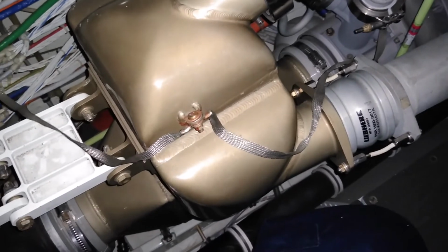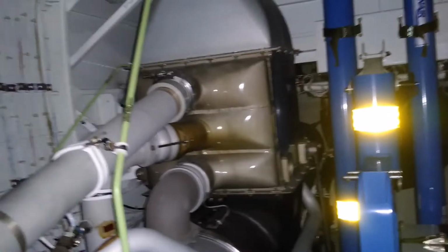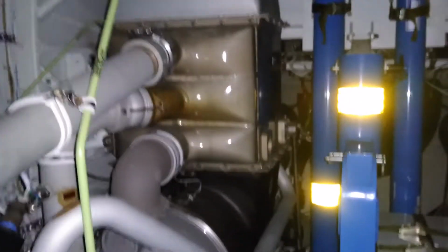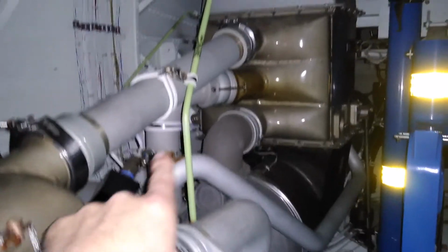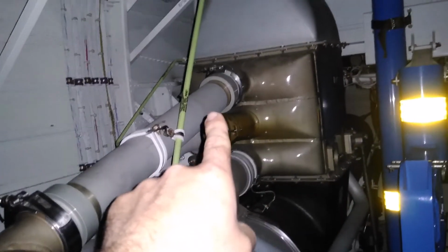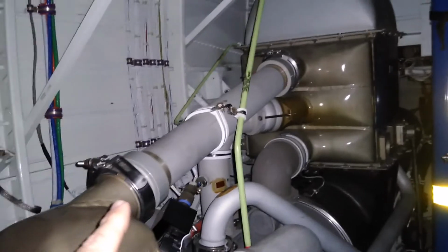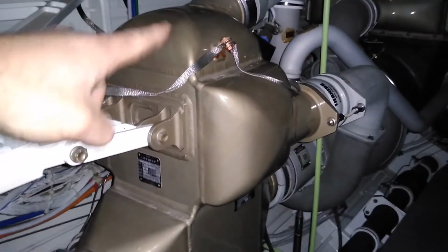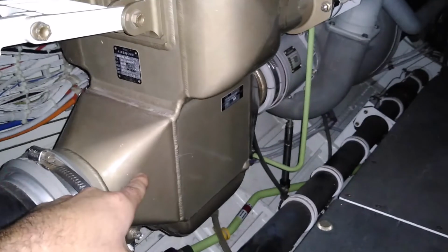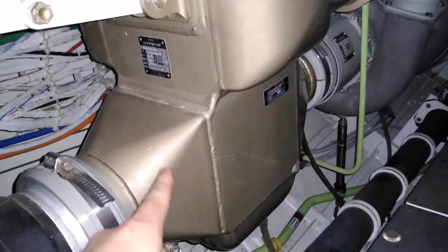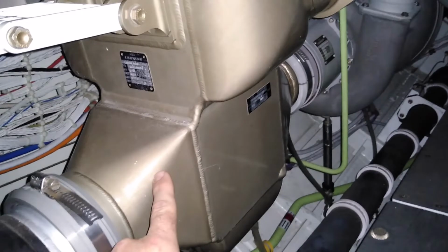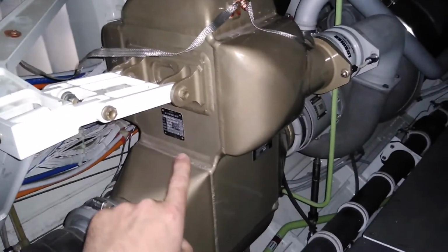Let me take a step back to make it a little easier to film. This is where we left off: after bleed air comes in, gets cooled off, goes in, gets compressed, gets fed back in, it goes through the dual heat exchangers, where it gets cooled off by the turbine's cool air to condense the water out of the air, and the water separators on the far side